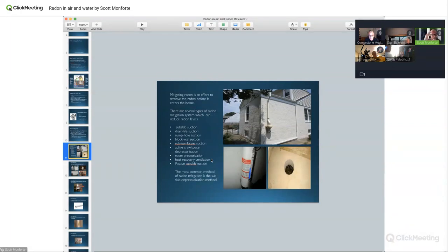Everything below that spray foam insulation that's between the rafters is now below that. Your radon fan is now kind of in a conditioned area. The other thing we do, right? We go do an inspection. We open up the knee wall doors in the attic. It's all finished on one side, and on the other side, you've got the air handler and the radon systems. If that fan would potentially leak, right? I mean, you may have a soffit. It may be spray foam insulation, so that gas could enter the attic.